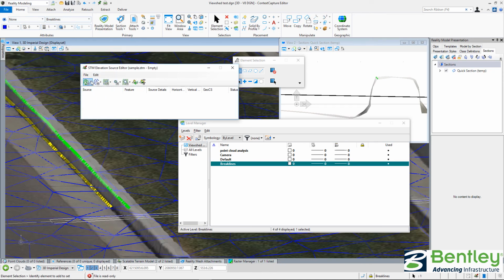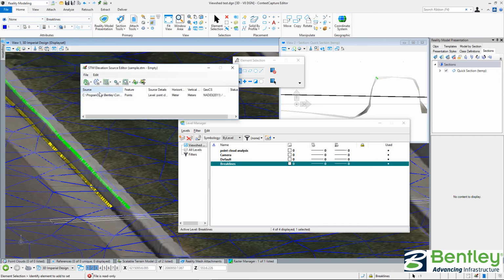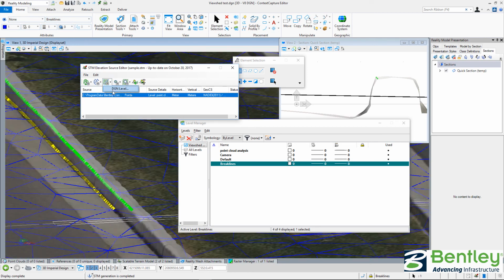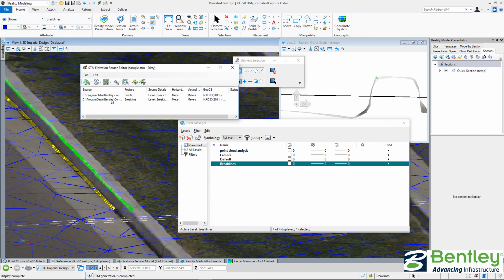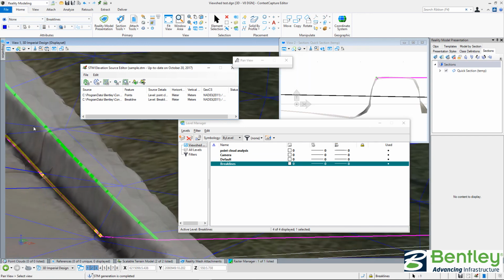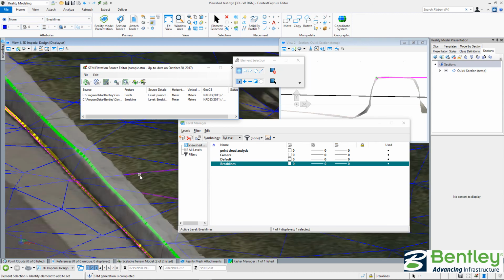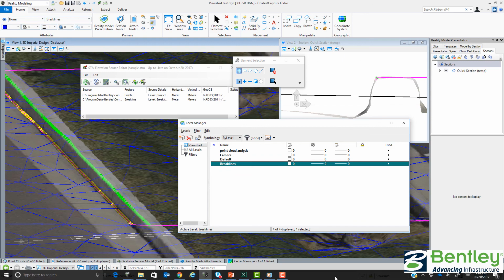But let me bring in, first I'm going to bring in these random points that I do have in this file. So now I have my random points in here. And then we bring our DGN breaklines. And just this easy, you would hit select breaklines. We then see that it says it's dirty, so you need to rebuild it here. And we see the triangles reform quickly. We see these, they're now purple lines, but you see it going along the base here of my triangles to hold the bottom of curb. The blue lines that you're seeing are the previous one that was read-only that I wasn't able to change. I think that does hit us right at the time.